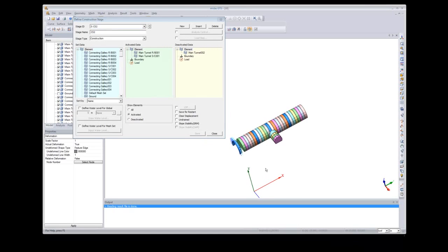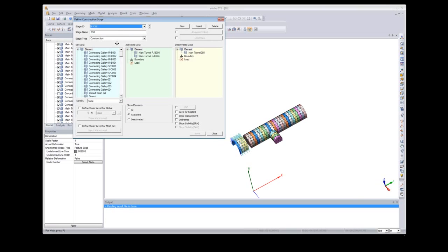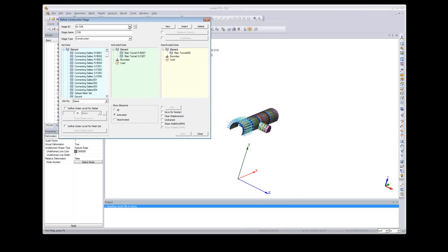Let me change the view, then you can see that better. And the first Shotcrete is created, placed there. Same thing going on, excavating and then adding this Shotcrete with these rock bolts. So the same thing going on, and as I mentioned, anytime you can change the construction stages. You can add or delete these boundaries or loads or anything that you are interested to change.